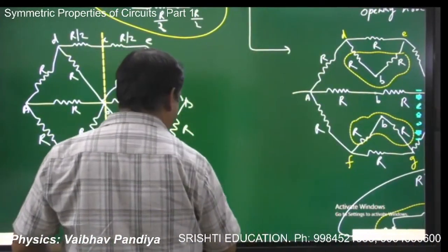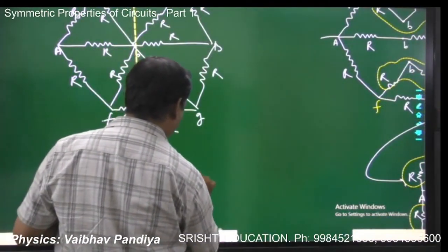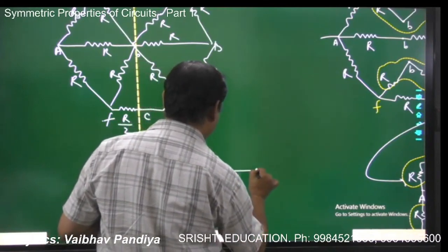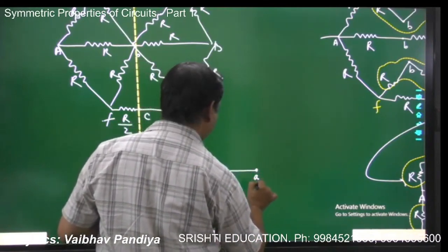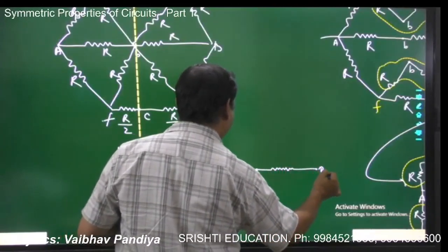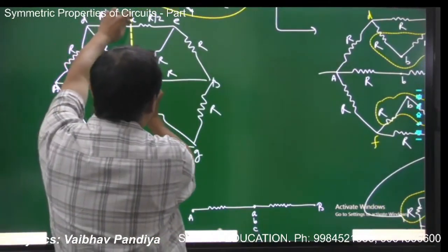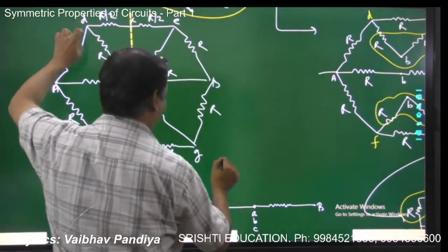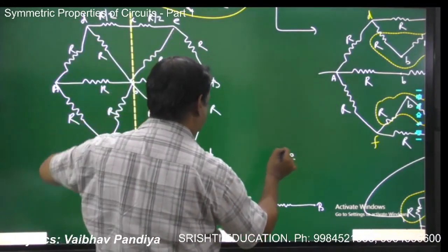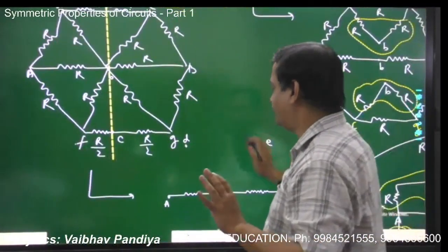Now what I'm going to do, I will make an equivalent circuit treating the points of same potential as a single point, or short circuiting, that is A, B and C. Now I will join A and B, and this is the point D. So this I'm denoting as D, and here I'm denoting as E, and I will take account of each resistor and putting the mark that that resistance has been taken into account to avoid any confusion.